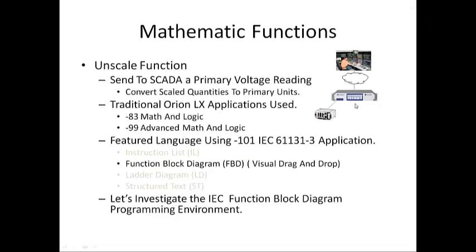If you are using, as in this case, a Biotronics meter, reading the scaled functions of per phase current, volts, watts, vars, or frequency, you can have the logic application perform the unscale application to view and visualize the elements in primary units.